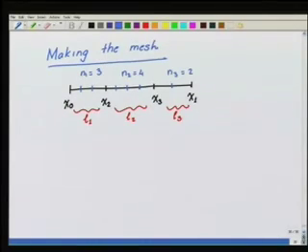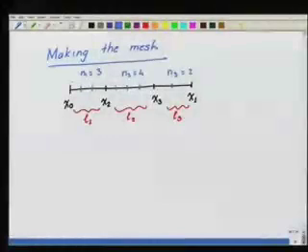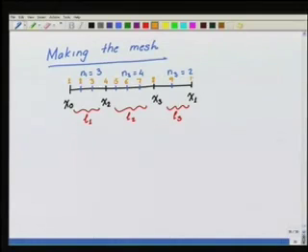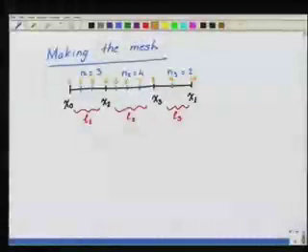Along with these partitions, we should be able to construct the coordinates of the nodes that we have created. How do we number the nodes? This is going to be node 1, this is going to be node 2, 3, 4. We are going to number them sequentially: 6, 7, 8, 9, 10. This should be possible while we are making the mesh. As we are numbering the nodes, we should be able to give the coordinates of the nodes.